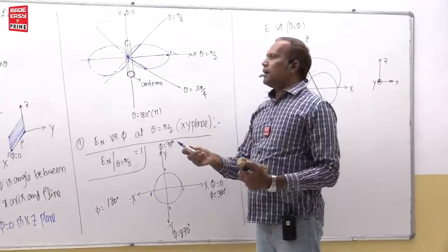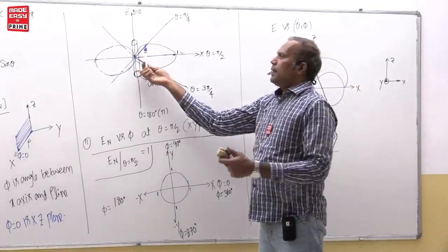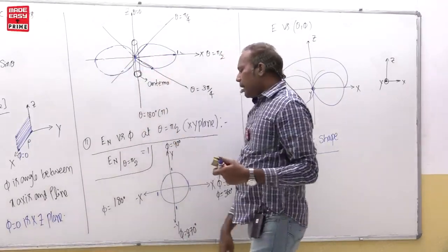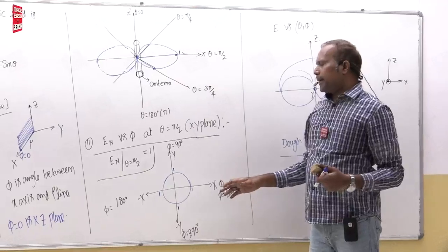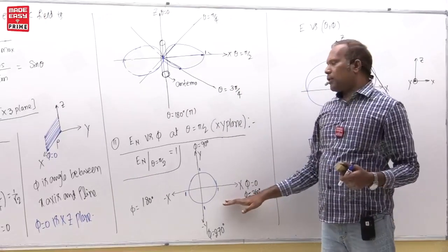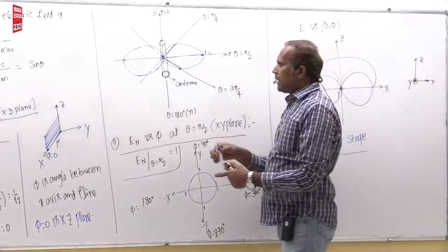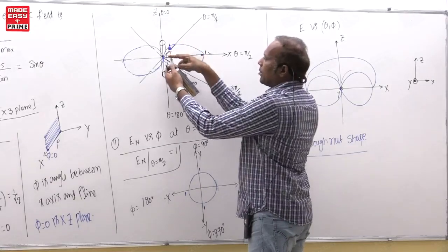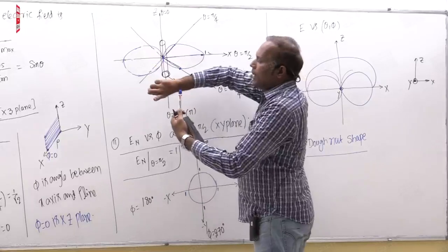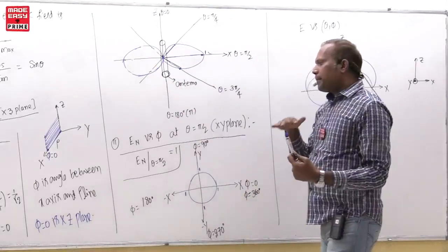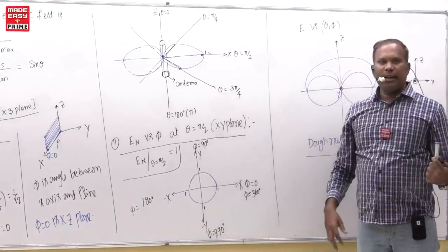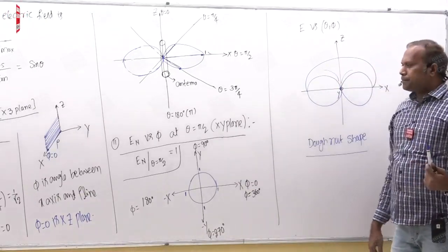If the antenna is like this, then at 90 degrees to the antenna length we have a figure of 8 shape. And automatically, if they ask the question, if the antenna rod is like this, then at 90 degrees to that antenna rod you draw a circle on that plane, that means the horizontal plane. The electric field value is actually constant, right?